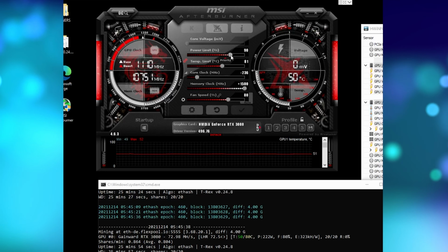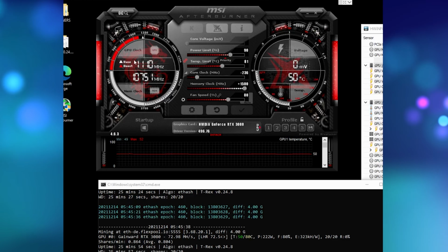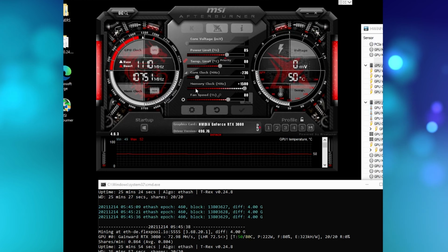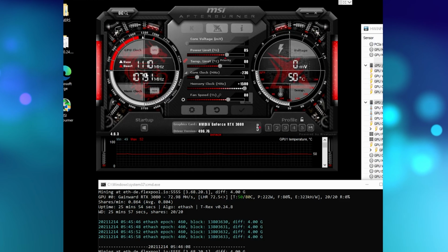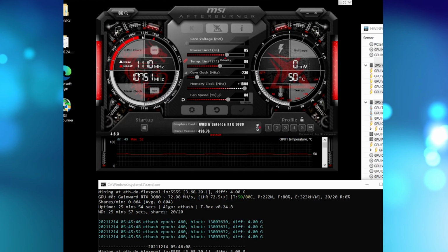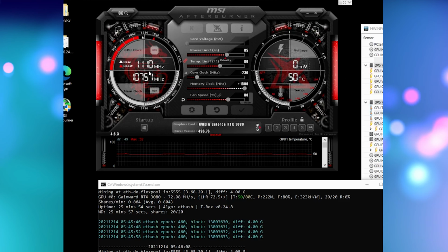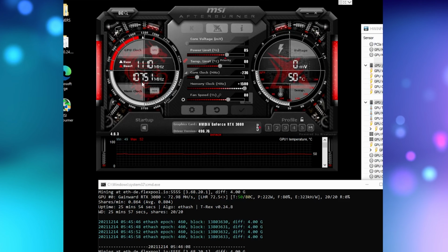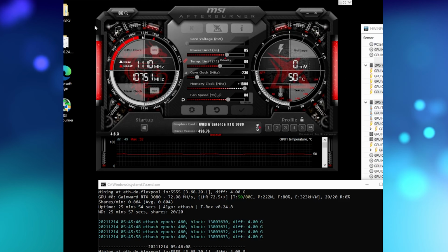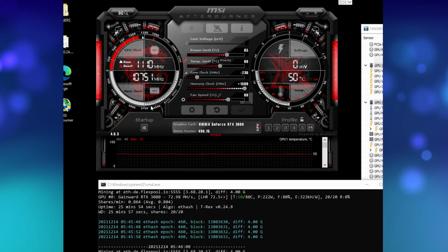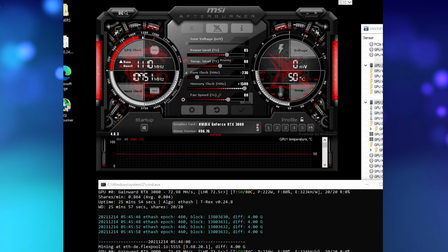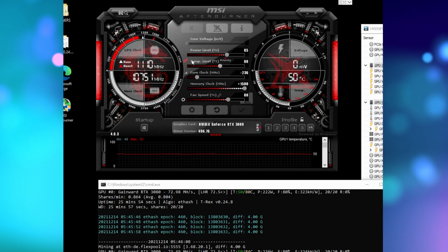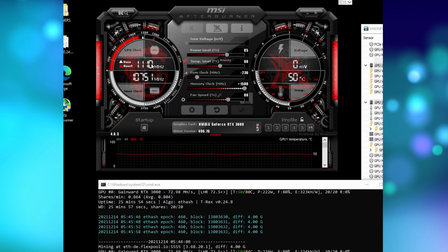If the power limit is being reduced too much, you will actually start to see fluctuation in this base limit. So let's start to reduce it even further, like, I don't know, 85%. Give it some time to stabilize itself. Sometimes it might take up to a full minute or 2 minutes to wait around and see if the GPU is stable. Other times you might experience crashes of the GPU, so the whole computer or the whole rig will freeze, so you'll have to reset and start all over again. Or maybe it will just fluctuate, and that's going to be a very strong indication that you have to tinker around with the power limit and actually increase it once you start seeing fluctuation over here.